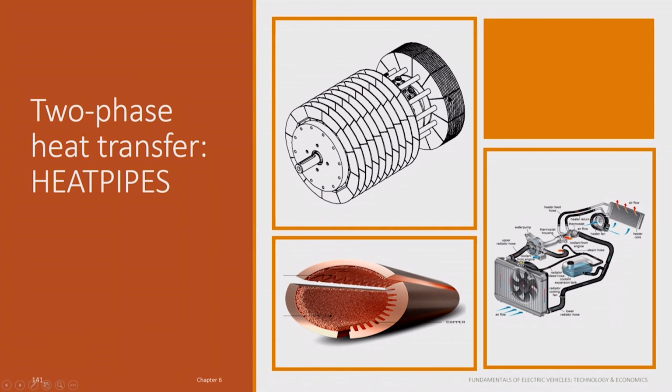These are the heat pipes, and then there are many closely spaced fins at the other end of the heat pipe, and inside here what is not clearly visible is a radial fan, axial inlet, radial outlet, which will blow a strong gust of air and take everything away. So, whatever you are seeing here which is being done by the liquid and the hoses is being done by the heat pipe, and then finally what is colloquially called a radiator, which is a long network of pipes with fins through which a fan is blowing, that fan is kept over here. So, you do not have any leakages, there are no moving parts.